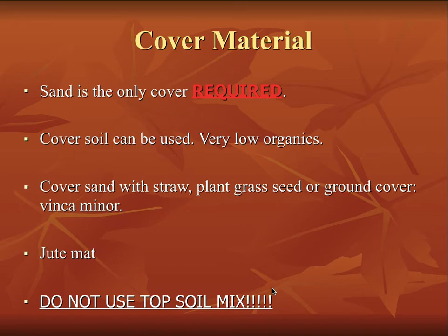We're talking about sod. We're fine with straw. Just throw some grass seed. We're fine with some vinca minor or a jute mat. But truth be told, just throwing some grass seed over the top of the sand, and that drain field will grow grass faster than anything else on site with that nutrient-rich water.